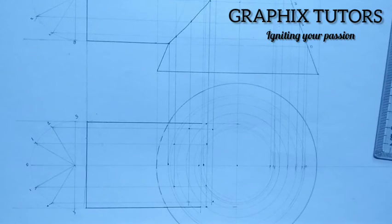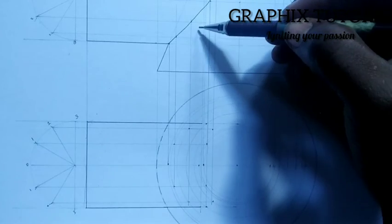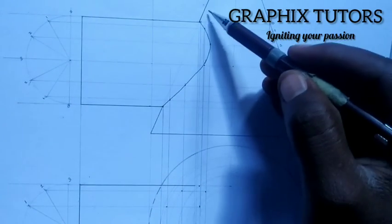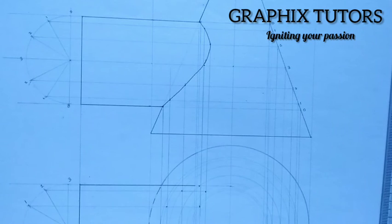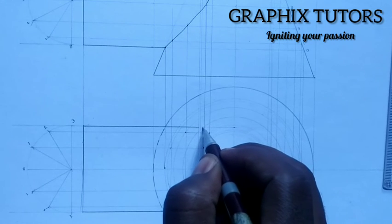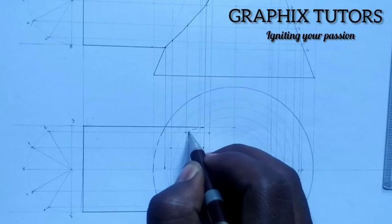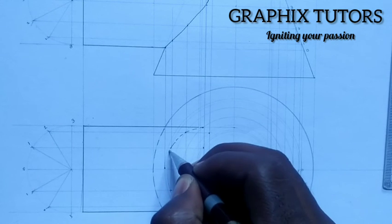Everything there will be hidden because all these points are inside the triangle, so you can't see them looking from the top because they are hiding inside the triangle. So if I'm to connect these points, I'll connect them with hidden lines. So with hidden lines, I'm going to have this. Use a French curve to connect.